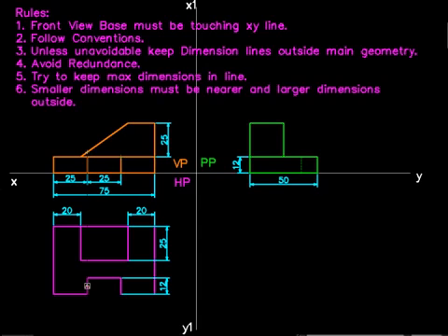So this edge must appear exactly above this edge. This edge must appear exactly below this particular edge, and wherever the other geometry is starting, like this starting point, it should appear exactly in a vertical line from the front view. Similarly, this edge should match the exact point here. As far as the side view is concerned, we have to take lines from this point straight, and we have to draw an arc with this point as center, starting here and ending here. So this is how we'll be matching the points.